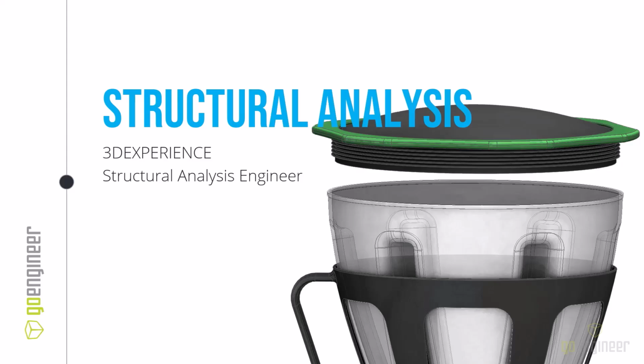So another structural analysis was the press of the lid onto the pitcher itself. Now we have the gasket seal, and I originally put 5 seals on this gasket. However, in talking with Matt Schreck, another engineer here, he said, there's usually only 2. So he actually modified the model, removed 3 of those seals. Now we know we need to press this lid on, and we want to keep the press force under 30 newtons, or roughly 6 pounds.